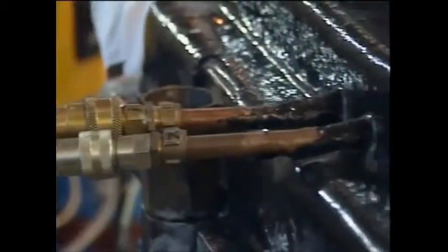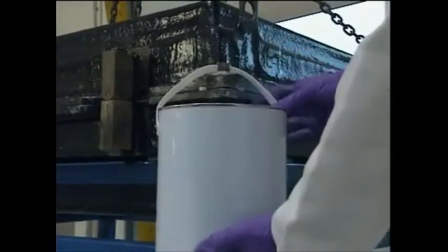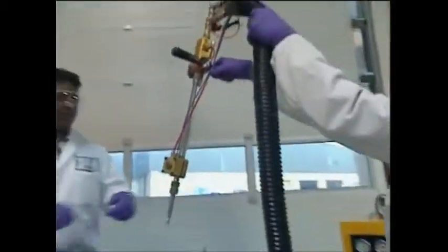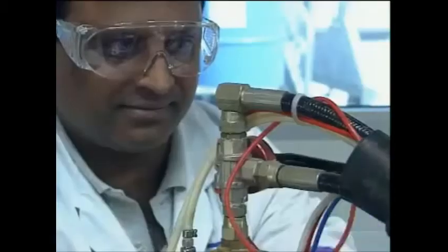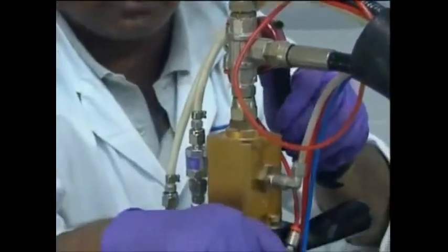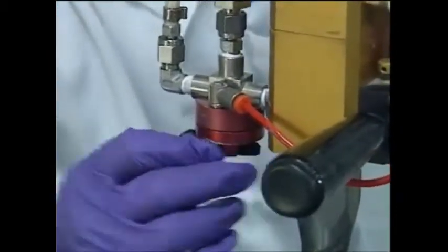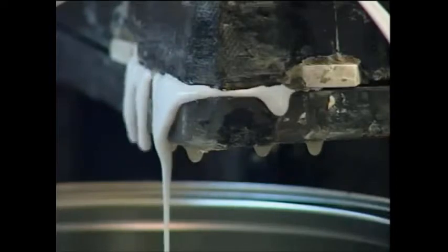Liquid heating is used to ensure consistent temperatures. 40 degrees C is a typical mold temperature. The mold is vented at the point of final fill. Resin is injected from a central point at typical injection pressures of between 2 and 4 bar. Machine options such as the mold pressure guard, or MPG, ensure that the injection is controlled and that the molds are not overpressurized. It would be expected to see a small amount of resin at the vents to ensure that the mold is full.